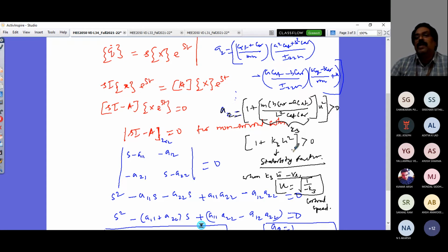So how do you ensure you are able to identify there can be an unstable state? Even if the design is of an originally oversteer tendency vehicle, you should be cautioned with this condition that the critical speed of such a vehicle should not be more. So you would be able to ensure the stability by riding your vehicle below this speed. So that is how you are able to look at it now.